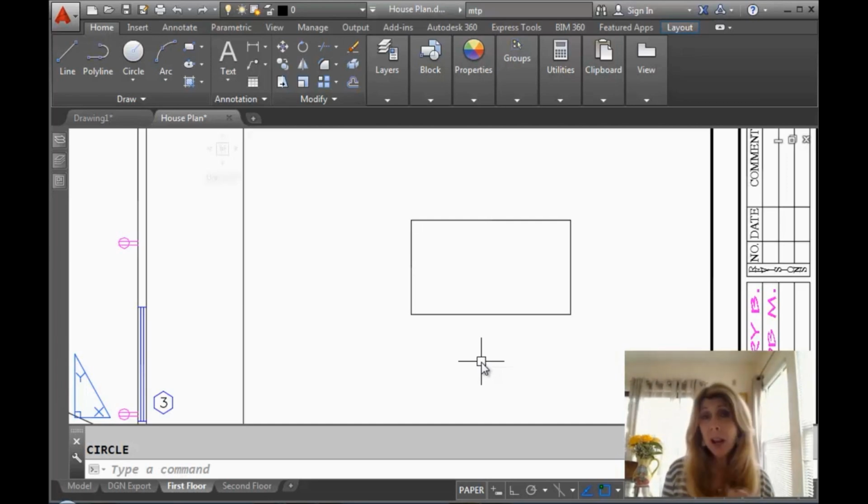Today I'm going to share with you a very cool object snap. It's an object snap override actually, and it's the midpoint between 2 points. I think if you knew about it, you'd find all different kinds of places where you could use it. It allows you to pick any 2 points on the screen. It could be on 2 different objects, in 2D or in 3D, and it will very quickly find the midpoint between those 2 points.